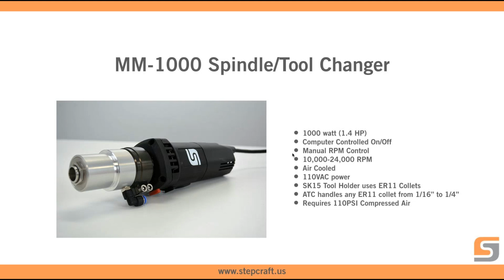The neck on this spindle, so you see the aluminum part, you can see where the push to connect is on this. The smaller diameter neck is 43mm. That's the neck of our tool holder on all of our D-Series machines. So that everything we have, all the attachments will fit into a 43mm tool holder circle. That's kind of one of the things that's like our trademark in terms of how things interchange. So this spindle could be used on any machine as long as you made a bracket to hold it that was 43mm, just to handle the neck of it. And again, I'll talk about that in a little bit.